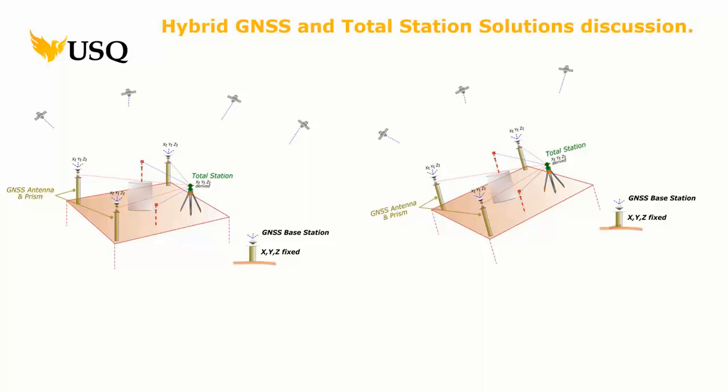Another clever way of looking at it, someone taking basically the Helmert transformation is a very old photogrammetric term, right? If you imagine it like this computer screen is what you're measuring, right? Because it's tilted all over the place, right? On here, there's a few things you know, which are these 4 corners, or 3 of the corners, right? And this is actually the design. You can do the transformation between here and here in real time. Therefore, you know what the X, Y, Z changes are, right? Helmert transformation usually is at least 6 parameters. So X, Y, Z, tilt, you know, so you have skewness and things like that. Basically numbers, that's all it is.